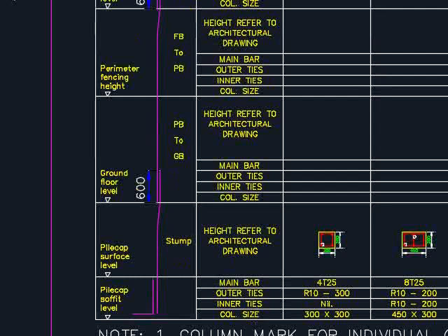And then what is indicated here, you have the reinforcement bar within the pile caps, and then you have the reinforcement bar to be lapped within the pile caps, and this will be extended throughout the stump and then go up by at least 600 mm from the ground floor level. Typically the stump is not that tall, somewhere around 1.5 meters. Sometimes it can be shorter than that.